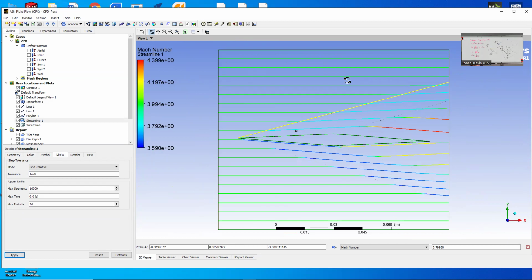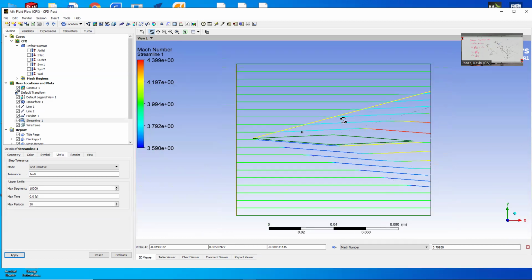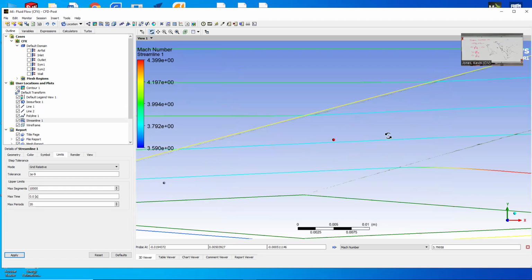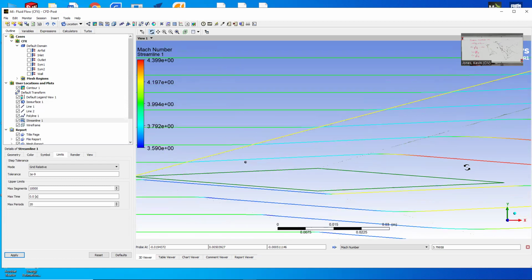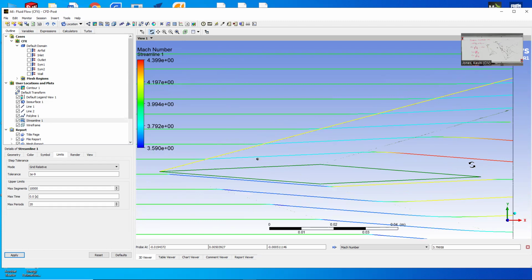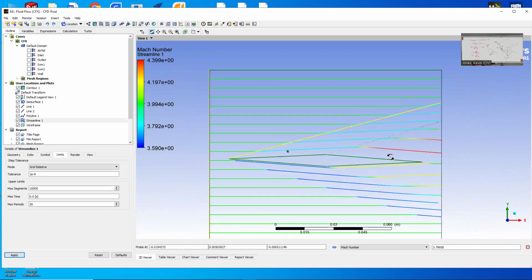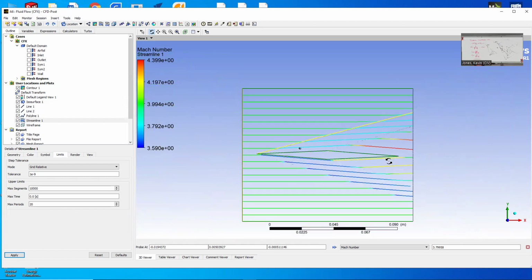So straight lines out front, straight lines behind the shock. And then curvy as we go through the expansion fan, and then straight again until they see another shock. So anyway, if you do a longer domain with more reflections, you'll always see that. You can always tell where an expansion fan is because you get smooth changes. I think that's about it. I don't think there's anything else.